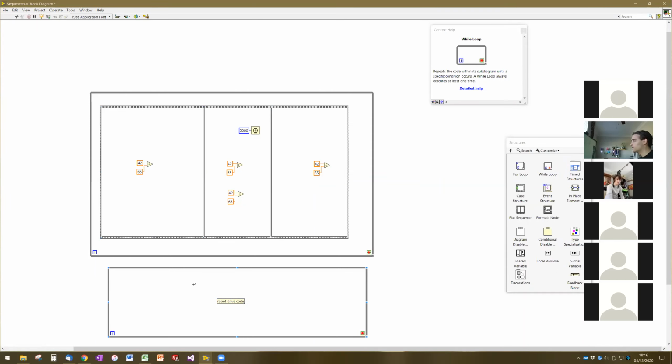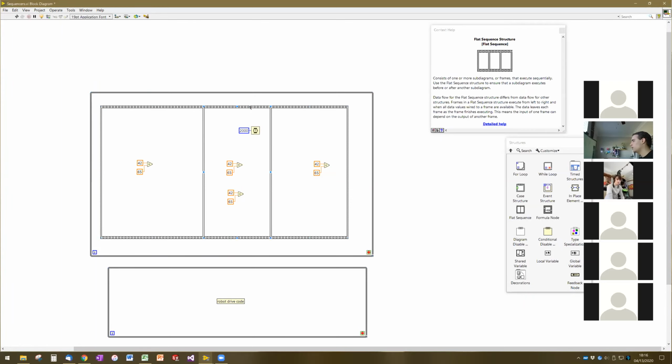The challenge with this approach is then synchronization between any decisions that are being made in the loop containing the sequencer and any decisions being made in the robot drive code. So, for example, last year, a lot of things happened with the drivetrain that were directly, when we climbed, the climb sequencer actually took control of the drive base at different points in time.